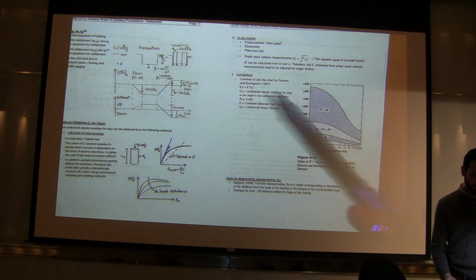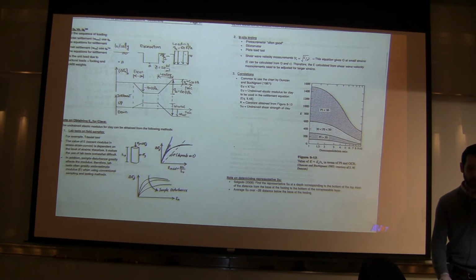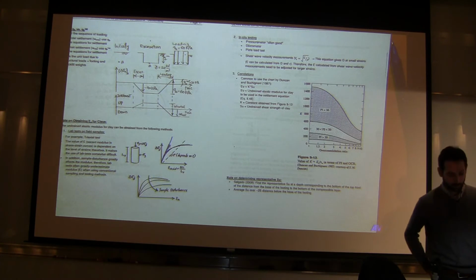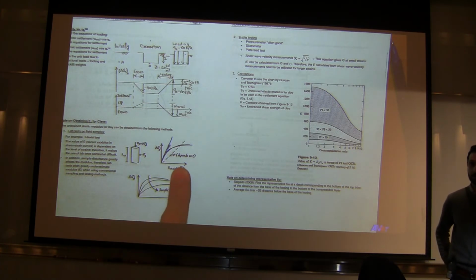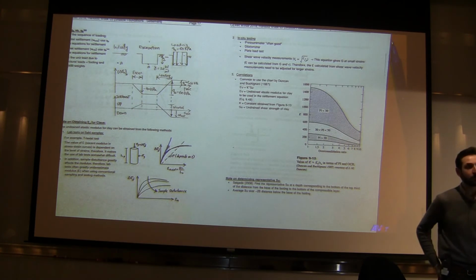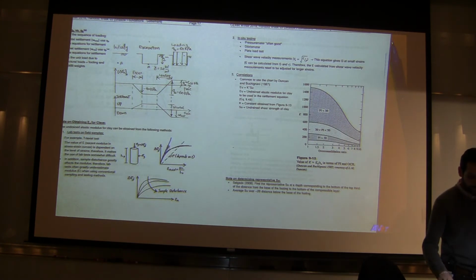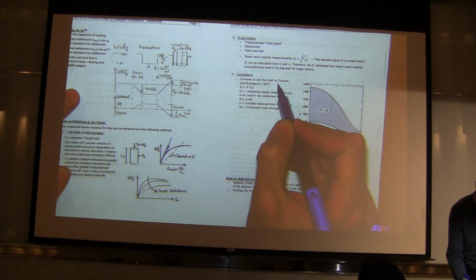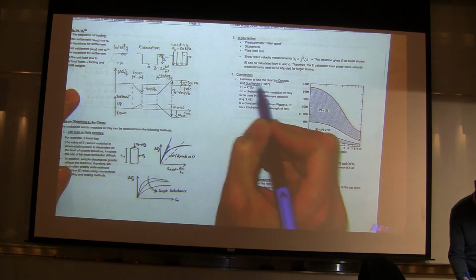And then we get to the correlations. Because the elastic modulus has all these uncertainties in how to measure and estimate it for sands and clays. For sands, we have to deal with the disturbance and the stress, and in clays, we have to deal with the disturbance and what strain level we want to calculate it at. We often rely on correlations and presumptive values a lot.